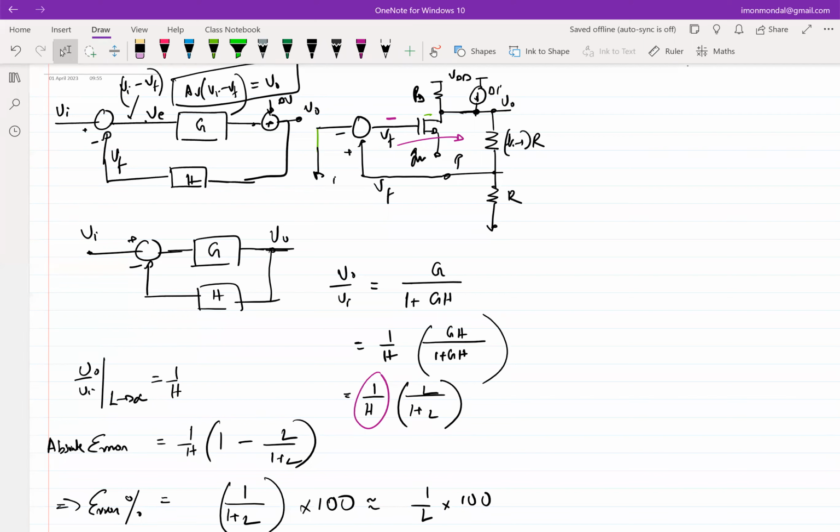So you have to design your loop gain for 100, and loop gain is in your control. Part of the loop gain is the amplifier, which means the gain of the amplifier needs to be at least 100. Obviously, you will not make an amplifier of gain exactly 100. You have to keep some margin, maybe 200 or 300 or 150, depending upon the variation of ambient conditions the amplifier can tolerate. But across all variations of ambient conditions, the loop gain has to be 100. Then you can always ensure that the error is less than 1%.